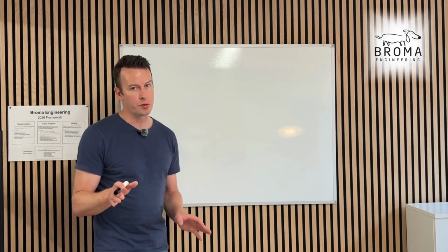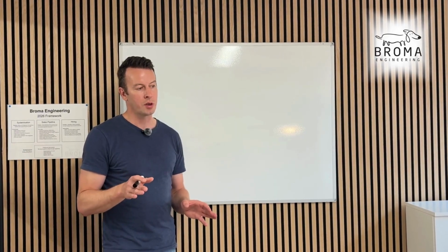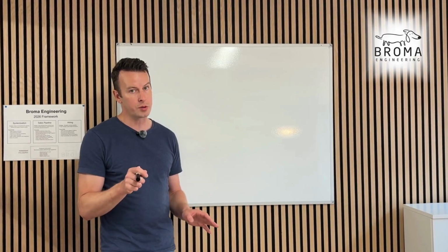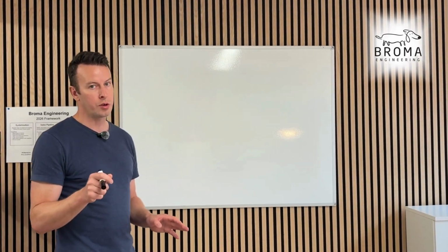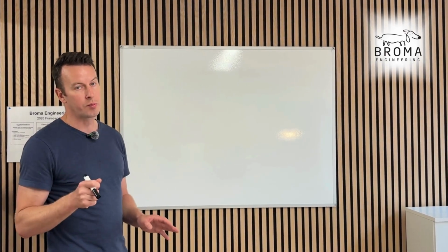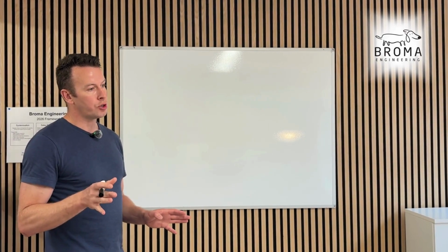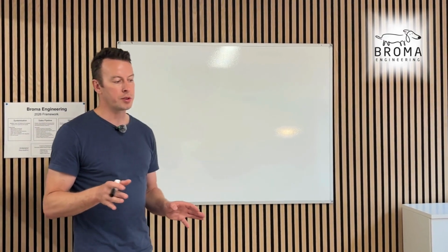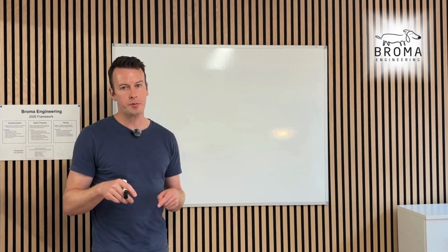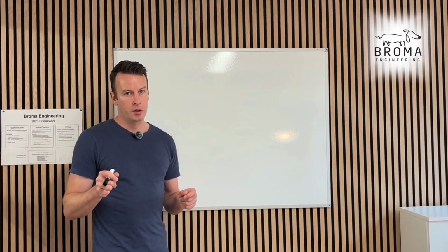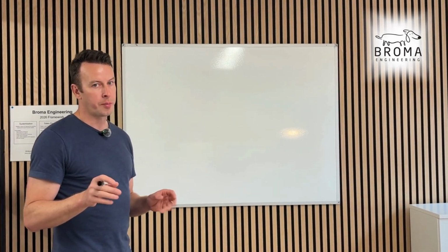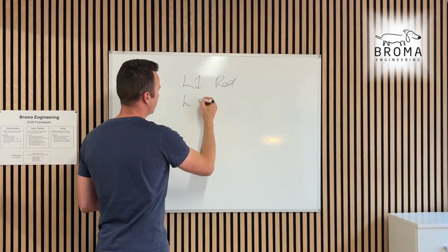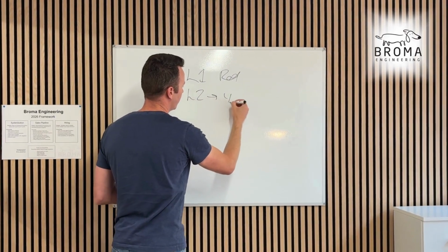So anyone who slows this process down is slowing down the project, is costing you money, costing you time, and it's a total waste. So be very careful with this. More is not good. Less is good. But what needs to be absolutely short check sheets, but relevant. All we're checking here is that the equipment is as it's supposed to be at this point in time. We're not checking anything else. Technical submittals, all that are supposed to be done by now. Level 1 is complete, red tag applied. Moving on to level 2, yellow tag.